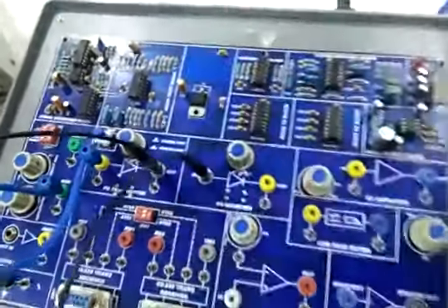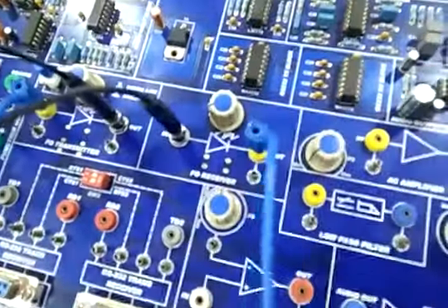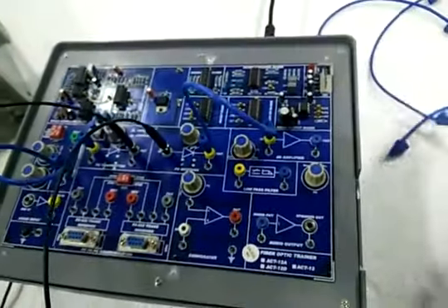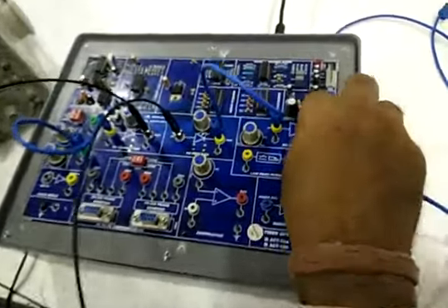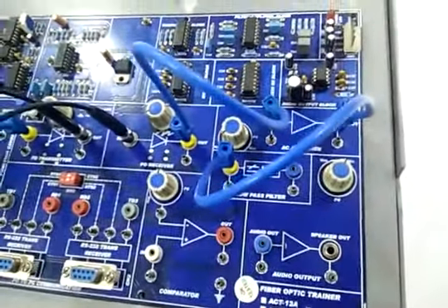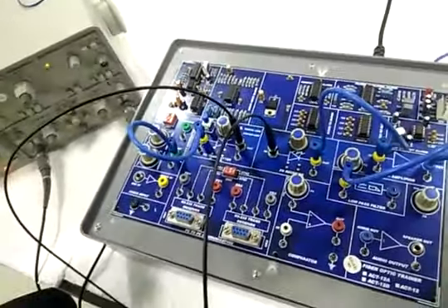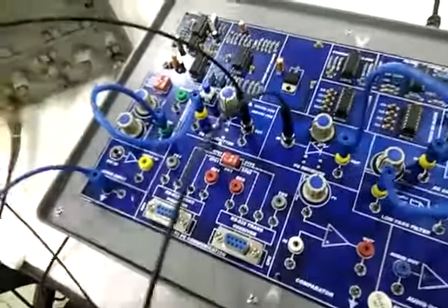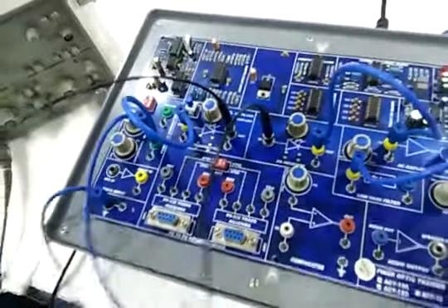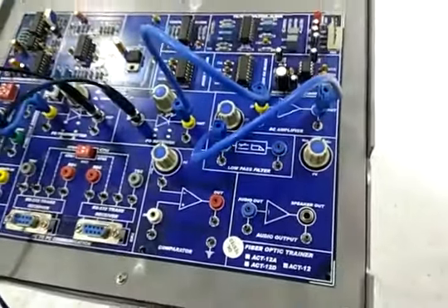through SMA connector. Now connect output of FO receiver to input of AC amplifier and output of AC amplifier to input of low pass filter. Now connect first channel of CRO to input of sine wave and second channel of the CRO at the output of low pass filter.